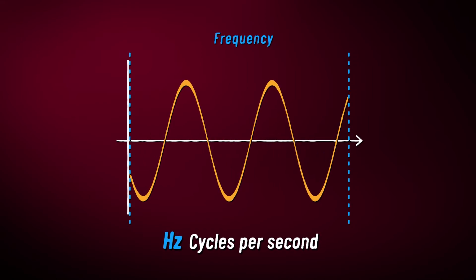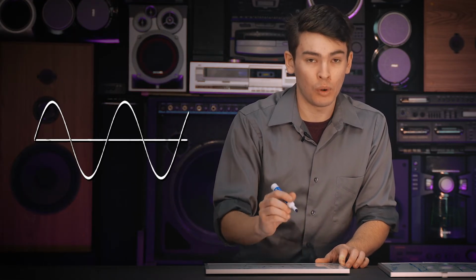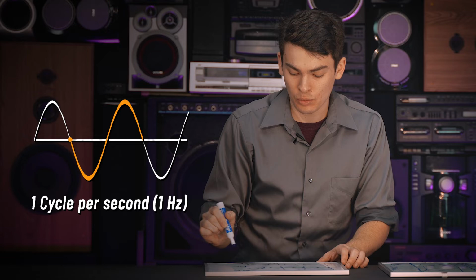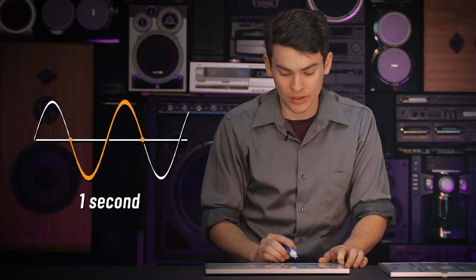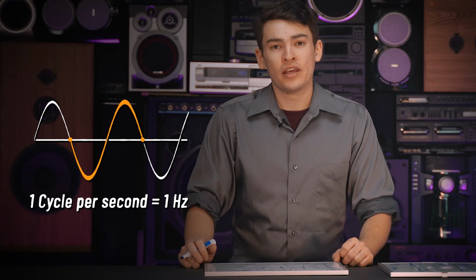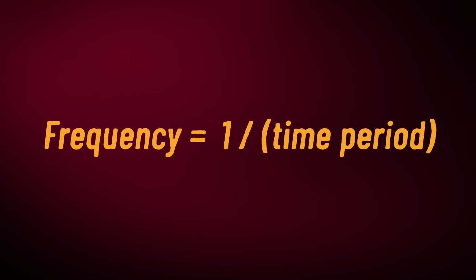We're going to use a very simplified example. If this AC signal was traveling at a rate of 1 cycle per second, the time it takes for it to cross that axis again, giving it 1 full cycle, equals 1 second. This gives us a frequency of 1 hertz as it cycles 1 time per second. The time period has an inverse relationship with frequency, meaning your frequency equals 1 divided by your time period.